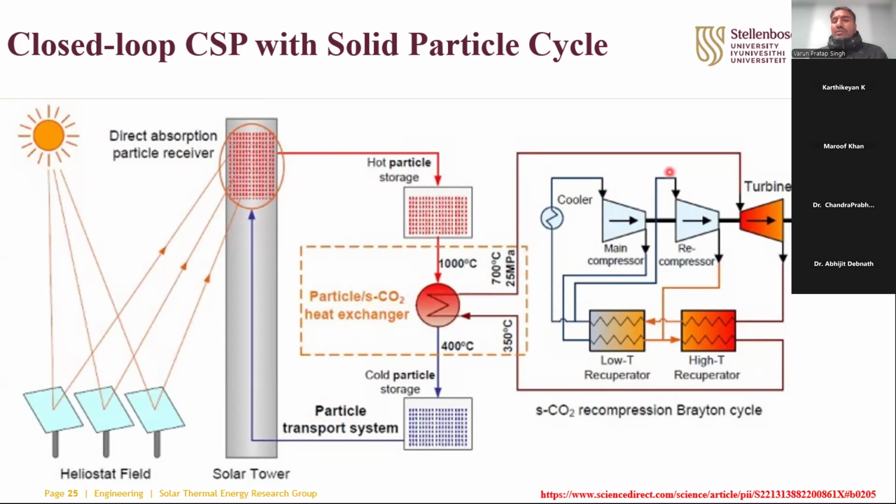very low compared to steam. We don't have any actual plant of megawatt capacity, but right now there is a 100 kilowatt setup at pilot study scale. So you can see another thing coming into the picture. We are changing the Rankine cycle to the Brayton cycle, but here the working fluid is carbon dioxide.